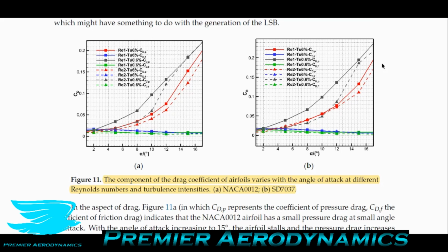The mathematics works out very similarly. And even though they're not the same underlying principle, you can measure them in the same way and calculate them the same way. Again, these are just vortices, and vortices, generally speaking, are just dead energy. You're wasting energy. So that's another form of drag.